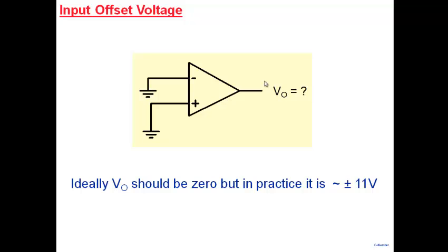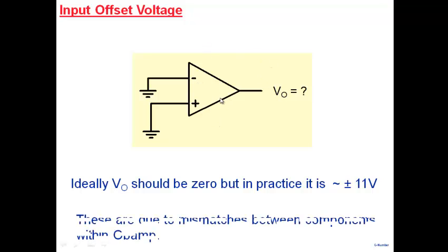And if you go back and look into the reasons for it, the reasons are that within your op-amp, as all of you know from your prior background, there is a differential pair and there are other amplifiers. And in a differential pair, one of the important properties is that there should be matching between transistors, matching between resistors.